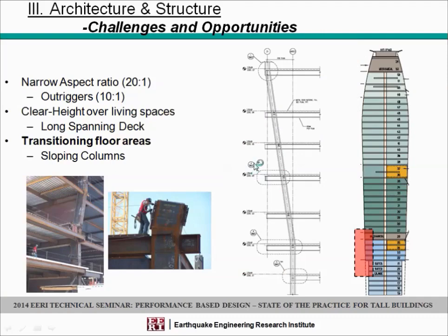The other issue we faced is the transitional floors. And instead of building cantilevers here that were almost 10 to 12 feet, we really developed the concept of a sloping column and cantilevering the floor rather than transferring all these floors.